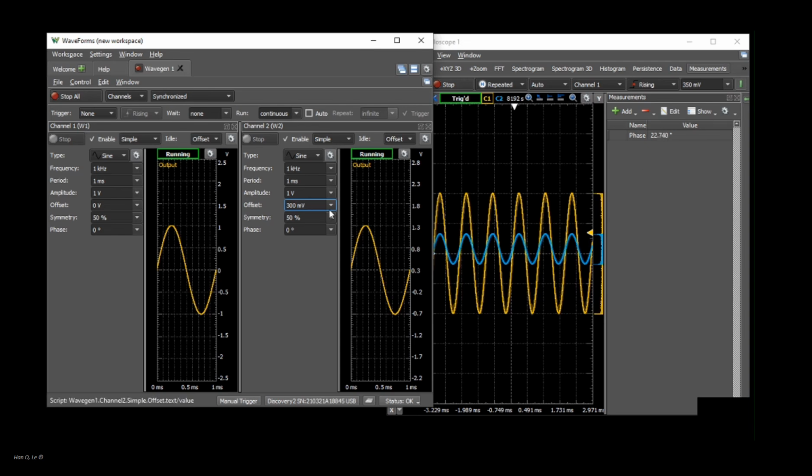As can be seen in the video, the larger the DC level offset was, the larger the phase error became. This is actually a common algorithm bug, or a better expression is, a common oversight. In processing any sinusoidal signal, it is necessary to separate the signal from its DC offset. In the Fourier transform, this is usually a subtraction of the signal by its mean.